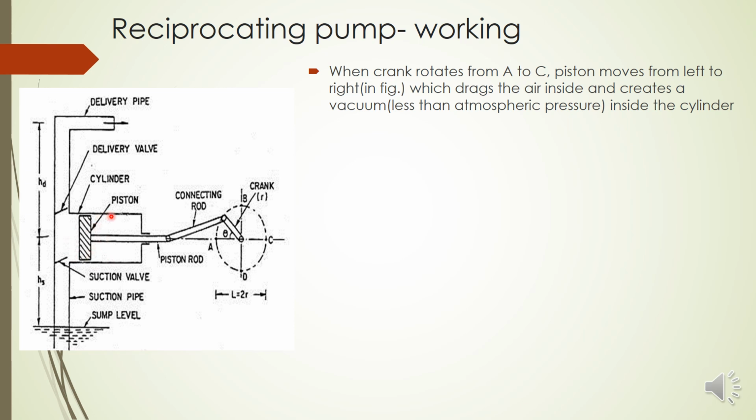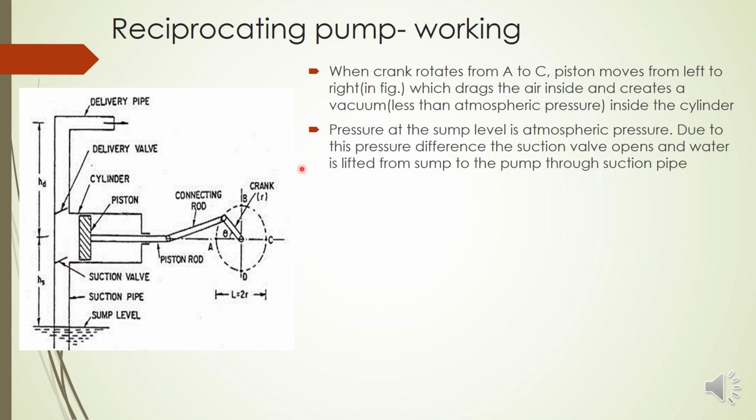Now the pressure at this region is vacuum pressure, but here we have atmospheric pressure. So you can see here we are creating a pressure difference. Pressure inside is less, here it is more. So the water will get lifted and it will enter into the cylinder. Due to this pressure difference, it will open the suction valve and enter inside the cylinder.